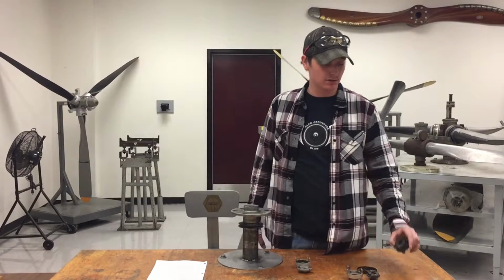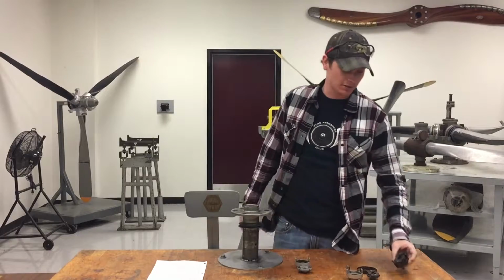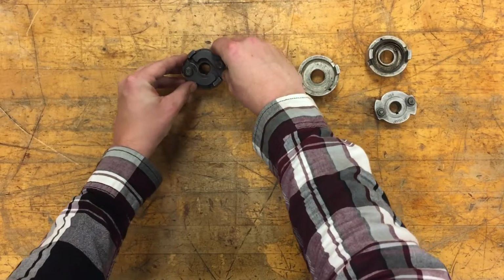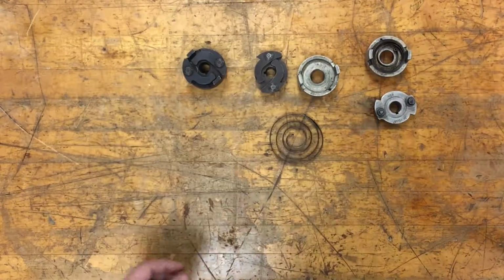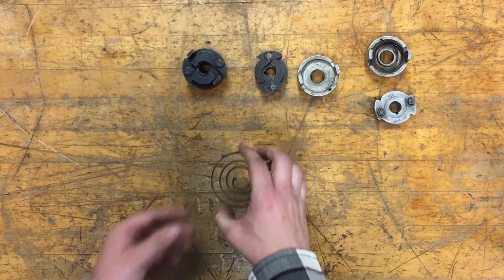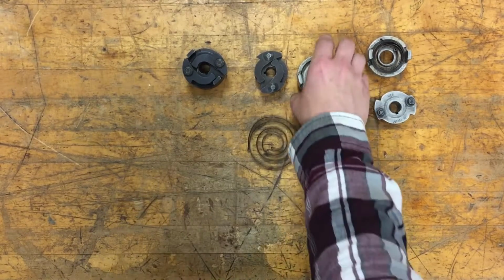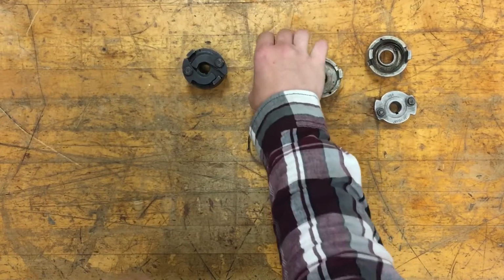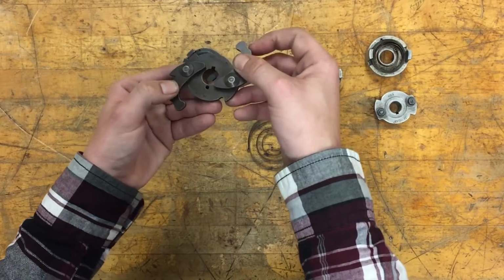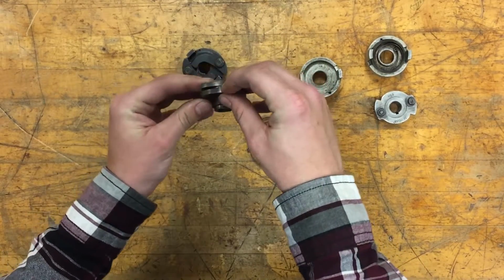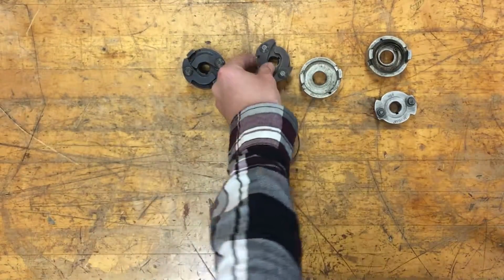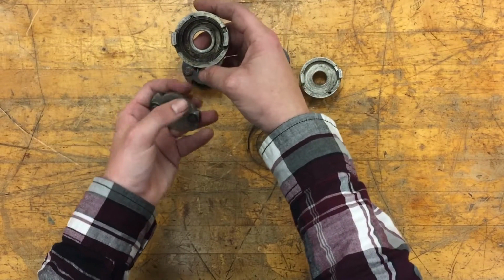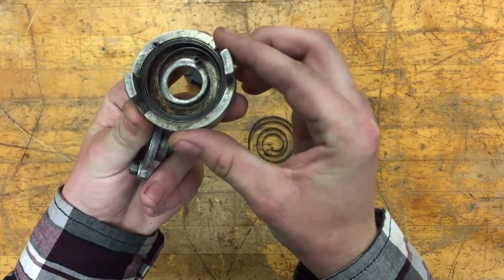I will be doing a video on the impulse coupling of the Magneto today. So this is a fully assembled impulse coupling with the flyweights right here. The stop pins are on the Magneto. This is the spring uncoiled. This is the impulse coupling body. This is the cam assembly with the flyweights. And the flyweights also have springs in there. And then this is a halfway taken apart one, which does not have the flyweights on it. And it shows you the coiled spring in there.